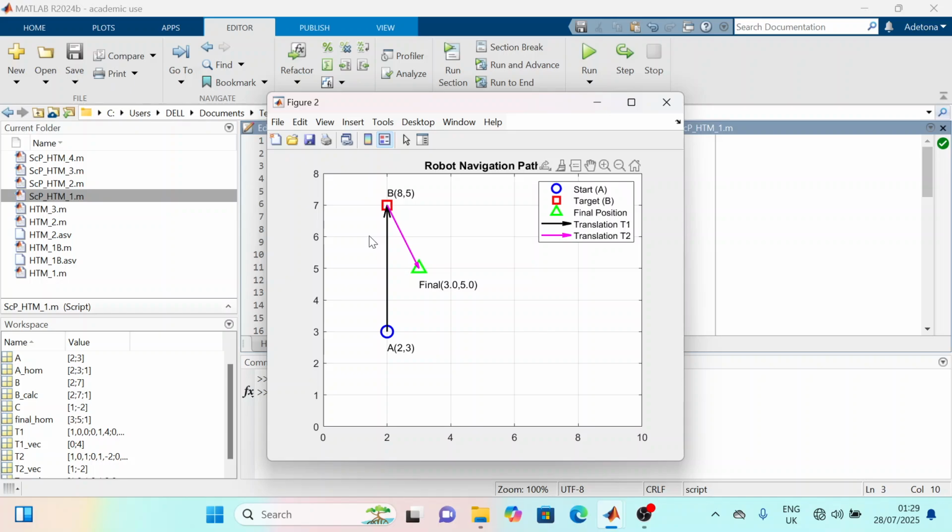After generating, they can make use of the homogeneous transformation matrix to translate the object they have generated, and by making use of the plot command for two-dimensional plots, they can plot and visualize the object in 2D. By making use of the plot3 command and fill3, they can generate and fill the object they have generated,